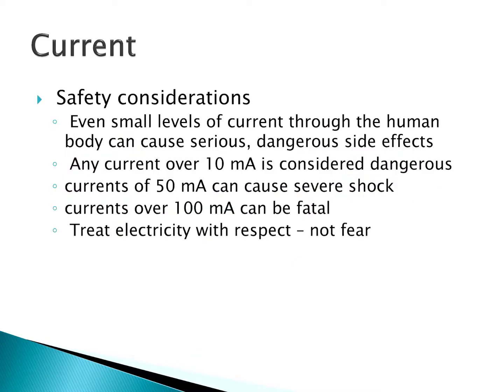This is something we did talk a little bit about in the lab, and that is even small amounts of current through the human body can cause serious and dangerous side effects. Any current over 10 milliamps is considered dangerous, and I told you that at 10 milliamps you can just start to feel it. Currents of 50 milliamps can cause you to feel like you've really got a shock, and currents over 100 milliamps, as I mentioned in the lab, can often be fatal and can kill you. So just a last line here: treat electricity with respect, but you don't need to fear it.